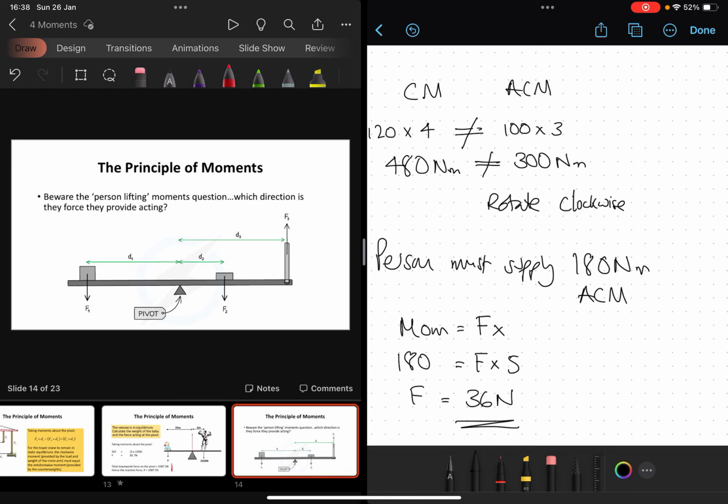So what engineers have to do then is think about all the forces that might act on that bridge and make sure that the 2 pieces of ground that the piers are sitting on can provide enough of a reaction force to stop that bridge from sinking. And they have to consider, well, what would happen if we had loads of cars all over here and none of them at the other end of the bridge? We're going to expect all these cars to provide a big clockwise moment there, and that's going to really affect the forces acting on the 2 piers.